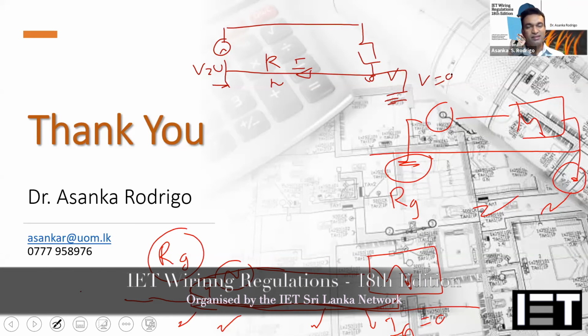Unfortunately, we adopted it. As I said, TT is not a very good earthing arrangement, so there are a lot of problems. This is one of the problems. But in the TN system, you can easily avoid this problem by earthing the neutral point at your distribution boards.